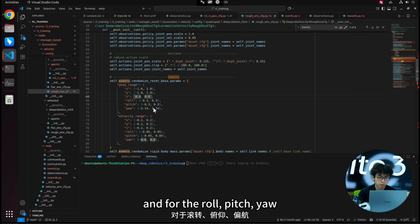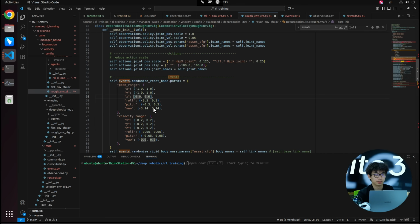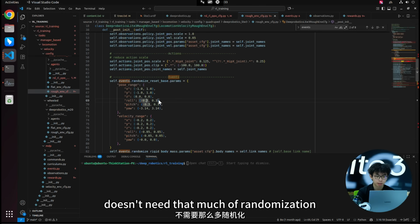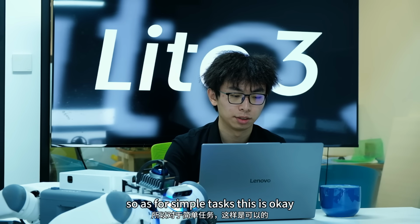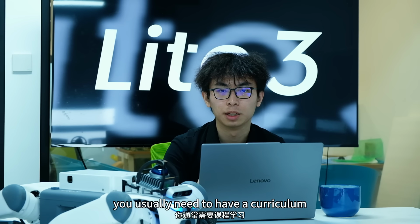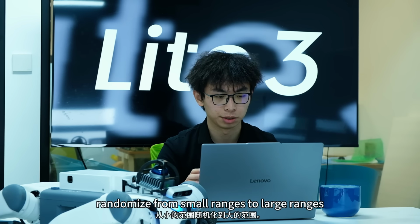And for the roll, pitch, yaw: roll and pitch are also X, Y, and it's going to tilt the base like this. We don't set it to be very large, because as I just said, it's a very simple task. It doesn't need that much randomization. Less randomization can lead to faster convergence, so for simple tasks, this is okay. For complicated tasks, you usually need to have a curriculum, and in the curriculum you also randomize from small ranges to large ranges.